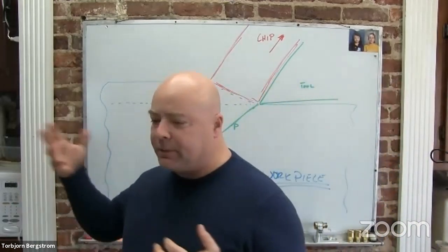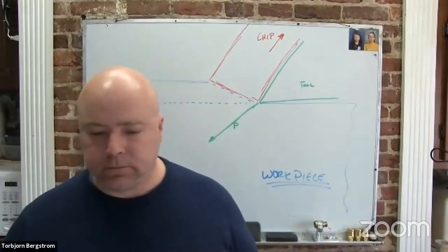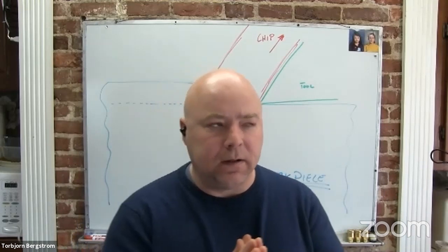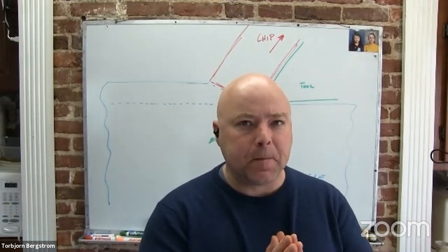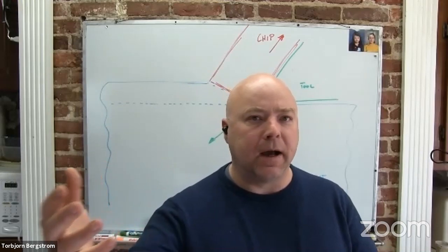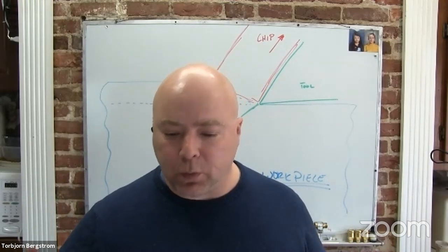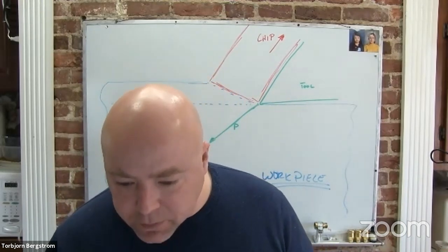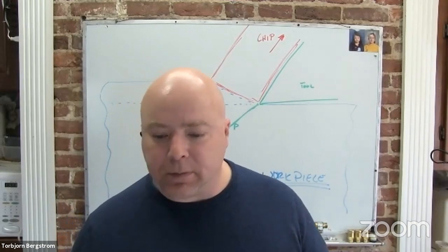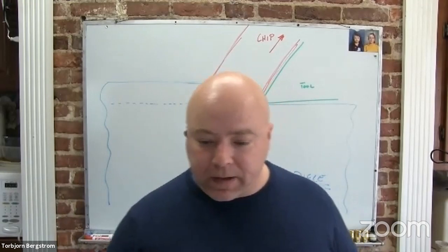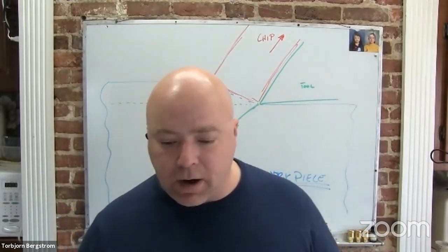So why would we want to measure the power when we were cutting? Philip. It can measure the cutting speed. You said something about cutting speed. So we could know the cutting speed by measuring it or by assuming it is what we programmed. But to want to know power, so somebody said by measuring power output, we could determine spindle load. So we could measure forces to get spindle load back. It definitely can have an impact on cost.